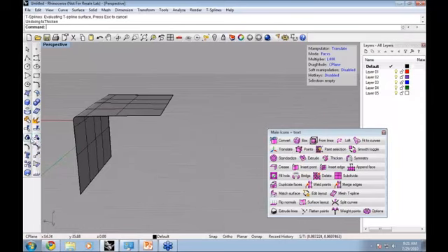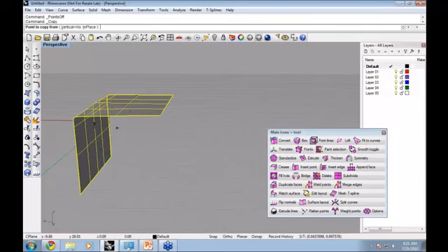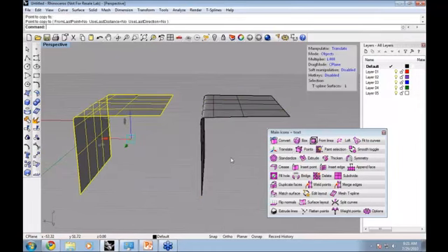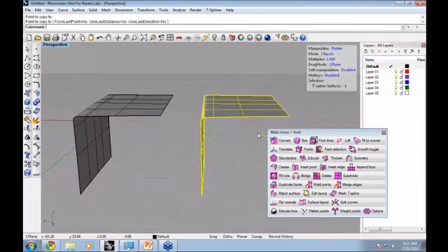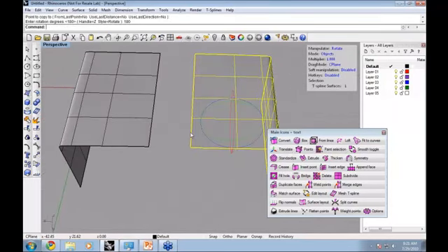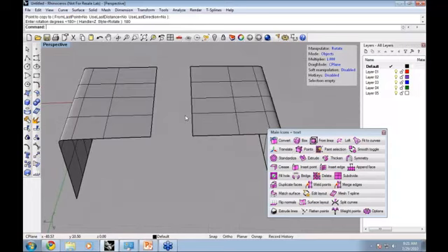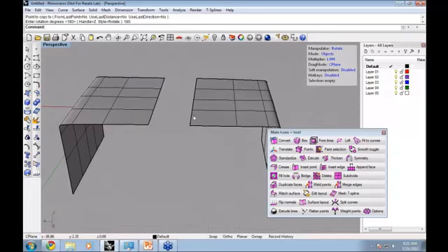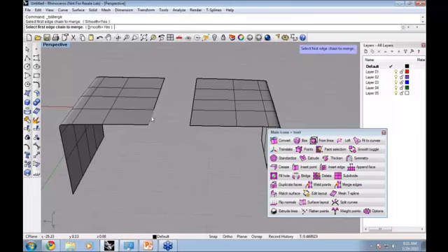So if we go ahead and copy this again, let's see, we need to turn off the T-spline's control points. And then again rotate this. Then what merge will do is it will actually merge these two edges together. So it does not need to be within any sort of tolerance. I mean, the closer you get, the less change there will be to the surface. But this merge edges command will let you select the first edge chain that you want merged, and then hit enter, and then the chain that you want the first one to be moved to.